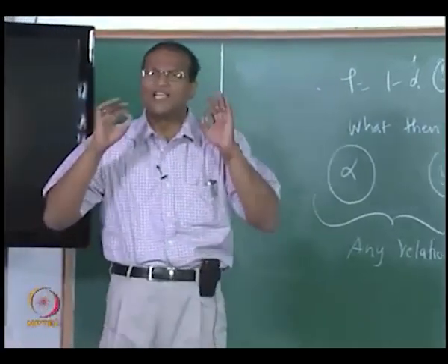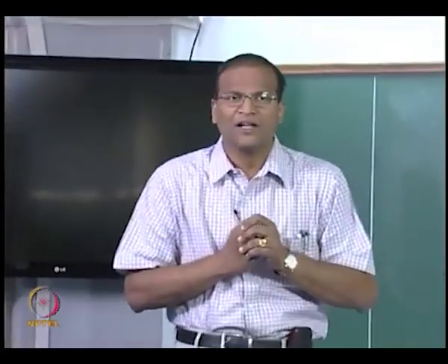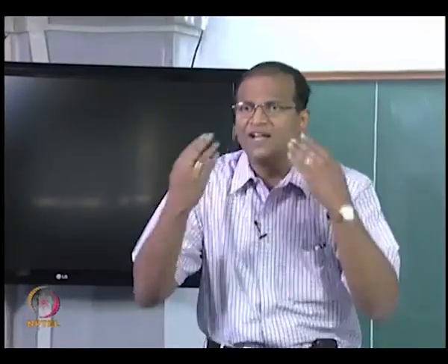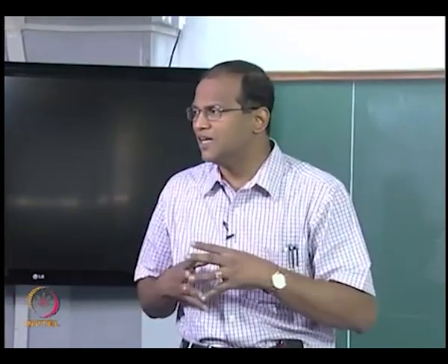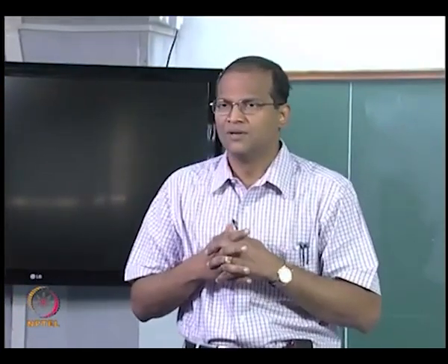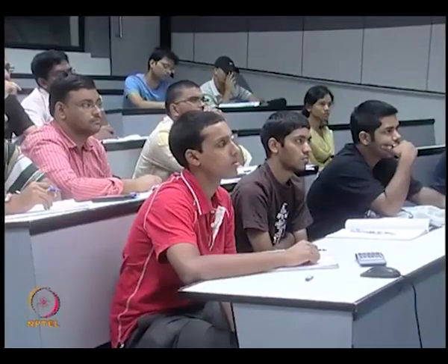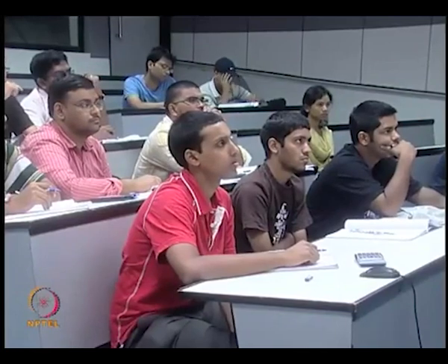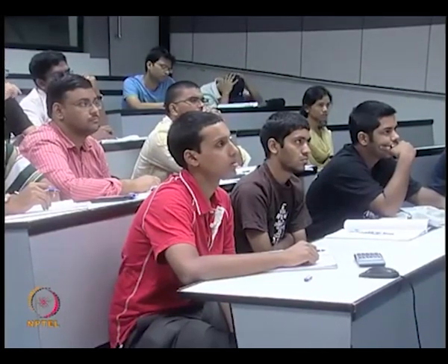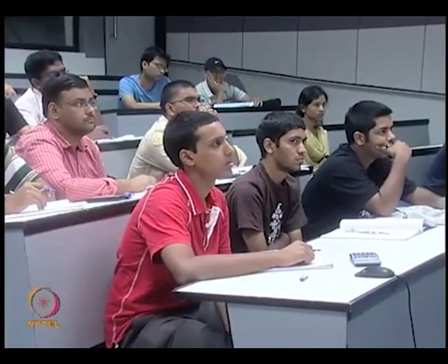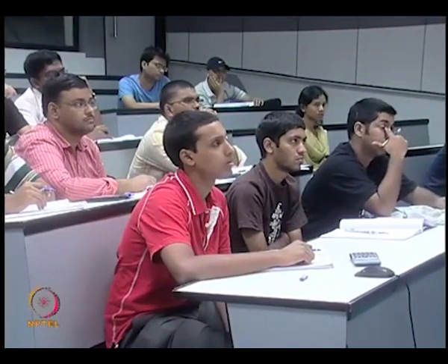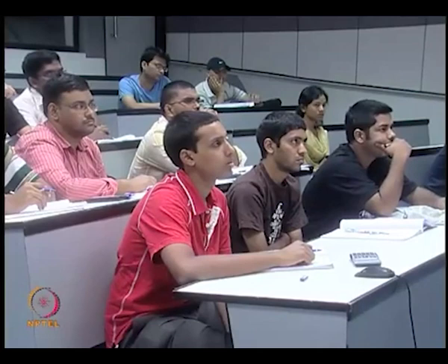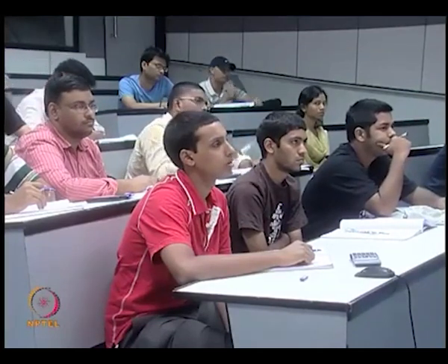Since the physical mechanisms of absorption and emission are different, we do not expect any logical relationship between emissivity and absorptivity to flow from theory. So the relationship must come from experiments. Fortunately people have done experiments and then they have found some relationship. Before we go into all this, first we look at what is called Kirchhoff's law. Okay, have you already studied this?